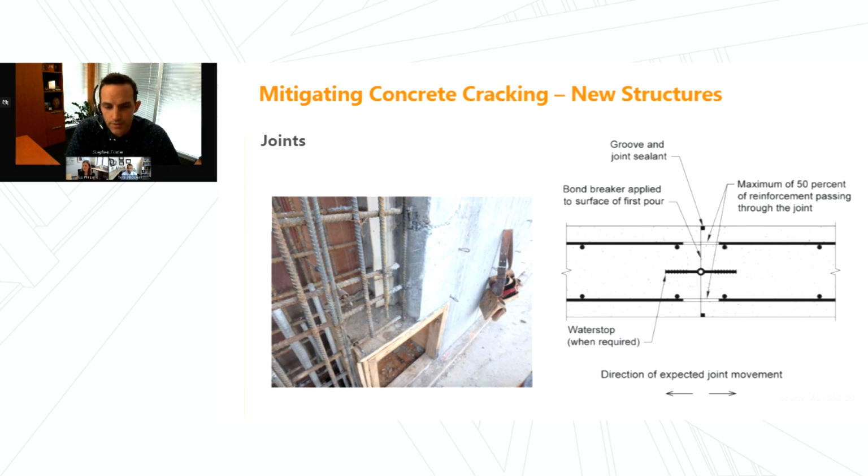Yeah, certainly a protective coating, and maybe we're talking about, again, two different things on a new versus existing. On a new structure, certainly the cast-in-place liner, there will be added costs there, obviously the cost of the liner, but in terms of formwork and casting the concrete and the overall cost of the project, that can be a good option when it's, again, an aggressive environment where we know there might be a combination of things, perhaps the chemical attack, which then can also contribute to reinforcing corrosion. And so using a stay-in-place cast-in liner, obviously that's for when it's newly cast, can be a good option.